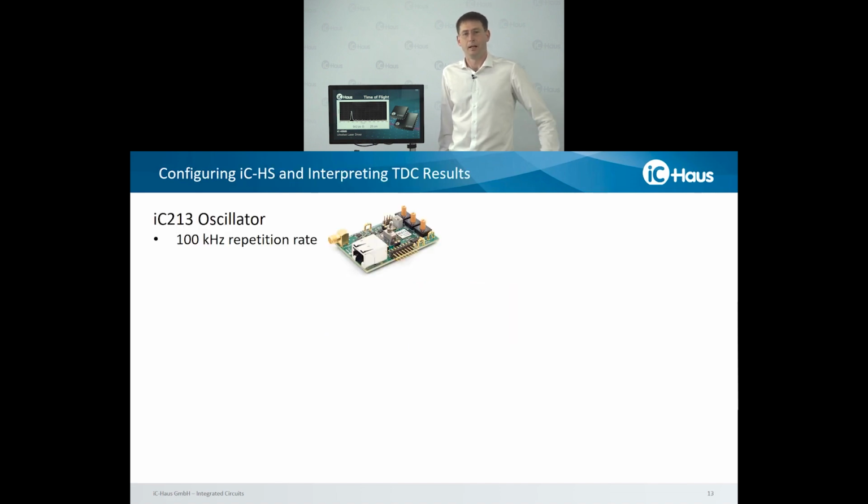So we, on the one hand, have the requirement, or we would like to have the requirement, that our laser pulse is displayed on the oscilloscope in a timely manner. So we need a repetition rate of our laser pulses fast enough that our sampling oscilloscope can sample it in less than a second, so we can pull out the data easily.